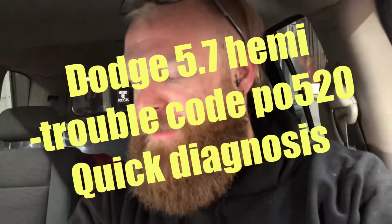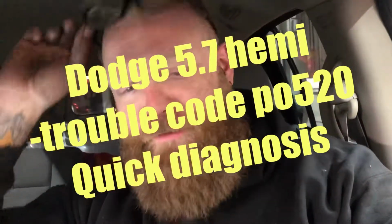We're here in the shop today working on a customer's 2007 Dodge Durango with a complaint of a check engine light and a little oil can light up on the dashboard. Really nice truck, 113,000 miles, seems to be in really good shape. So we're gonna take a quick look at this. There's a relatively common problem with these in the oil pressure switch, which I'm really suspecting. But we're gonna take a quick look.